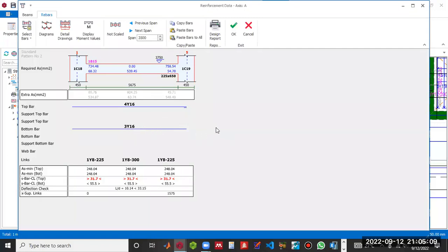The reason is that it adopts the support reinforcement as the compression reinforcement in order for you not to have so many cut lengths. That is, from this support, you will have 1/3 here, cut the reinforcement from here 1/3. The remaining place, it will not be up to 2 meters. Then it's much easier just to put the support reinforcement at both the compression face.